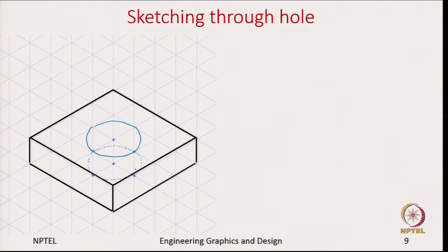So, this is the circle on the bottom face. Can we see the complete circle of the bottom face? No. What we see is only a portion of it. This portion of the bottom circle is what we get to see from the opening made by the top face of the hole. The rest is all invisible. Since it is invisible, let us erase those things.